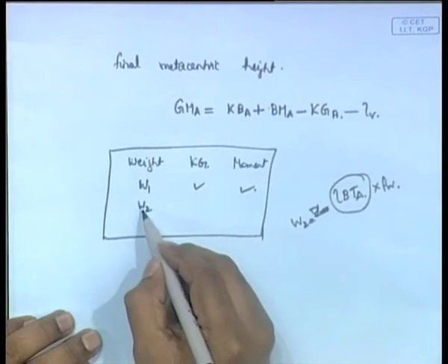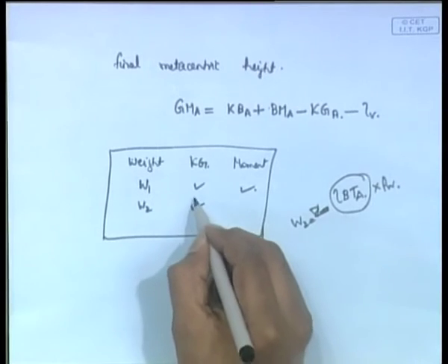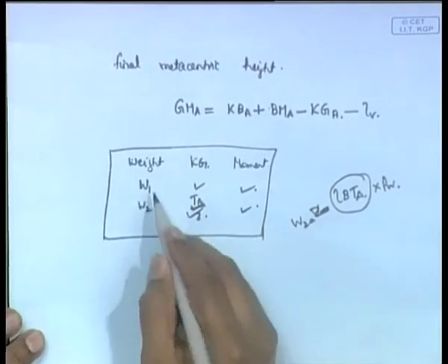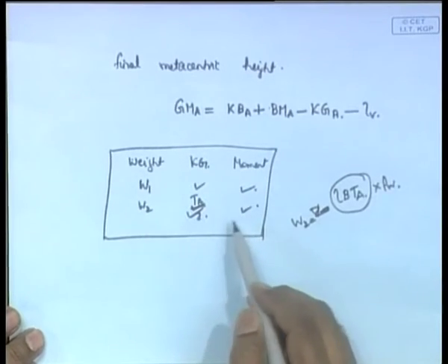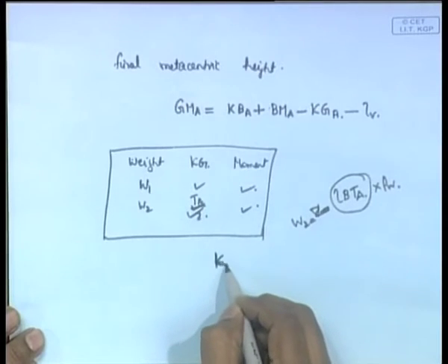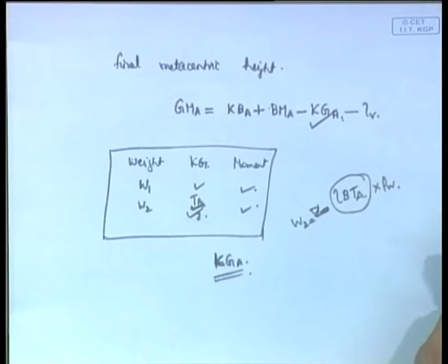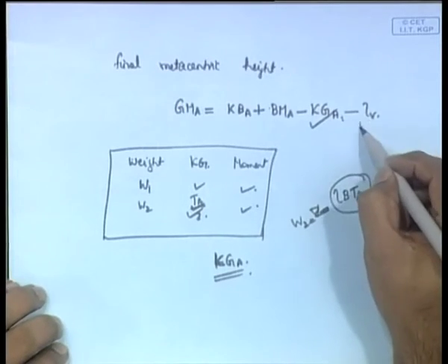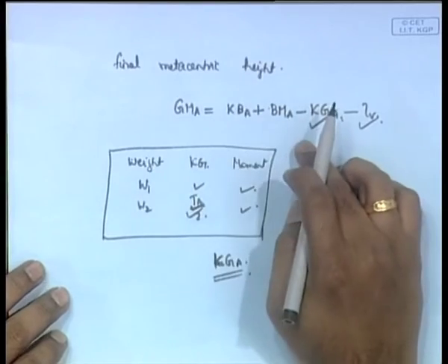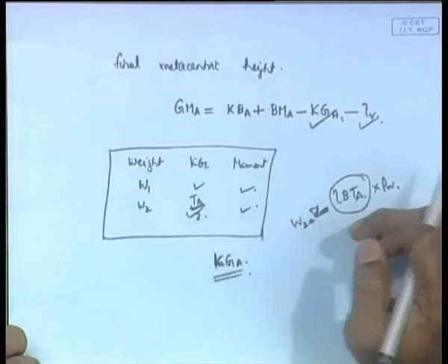This will be at Ta by 2, this will give you the moment, and then you find the net moment divided by the net weight, which will give you the final Kg. And the lever arm Lv we have already calculated, this is due to free surface effect. Now, when you do all this, you will get the final Gm of the vessel after flooding.